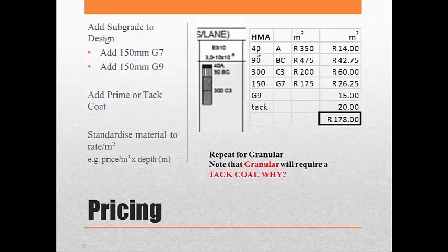So where we are putting down, for example, a 40 mil asphalt layer, all of those catalogues will have the same wearing course and the same subgrade. So the price comes down to the base and the sub-base. So when you're costing, this is really where you need to cost in our design context. You make your final selection and then you add your subgrade for a final price.